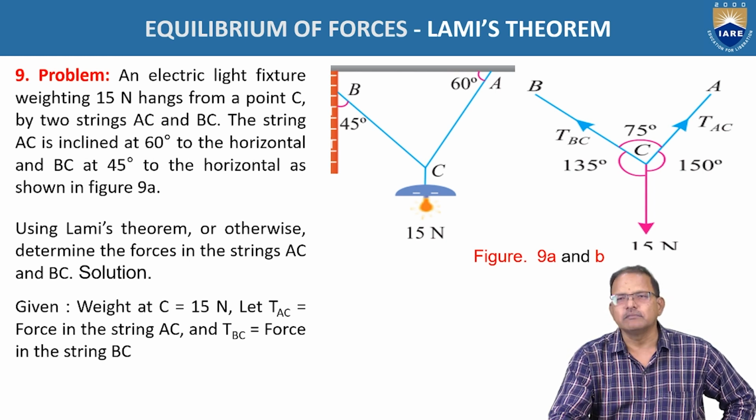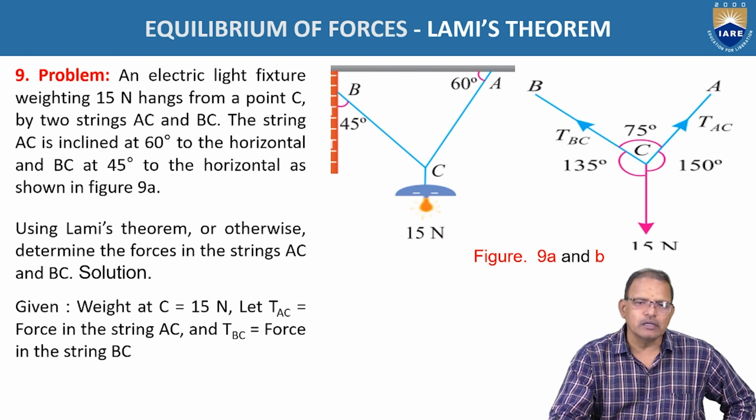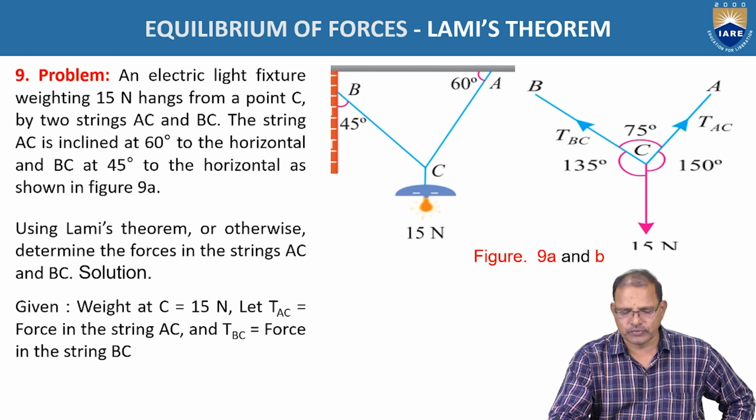According to Lami's theorem, when three forces are acting simultaneously at a point, as shown in the figure, when the body is in equilibrium, each force is proportional to the sine of the angle between the other two forces. That is according to this problem now.